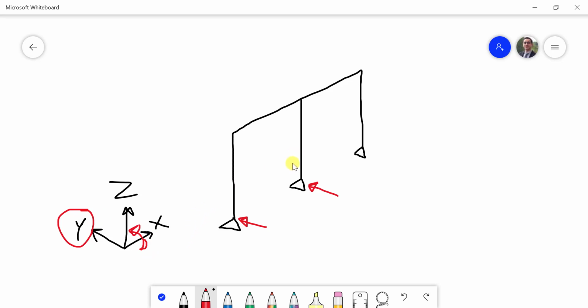And then the analysis will start, and while the solution of the equilibrium equations is going on, you can get some small forces acting out of plane, like some small instabilities because of the accuracy of the solution.